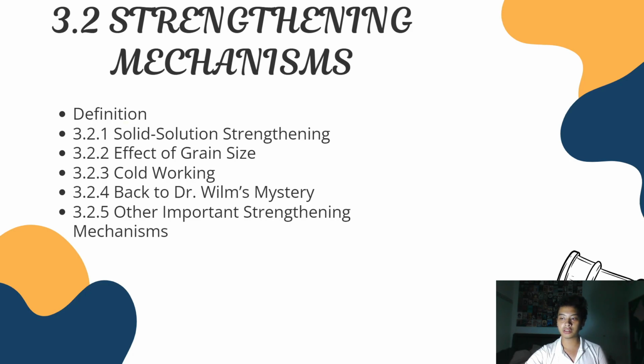Solid solution strengthening. Solid solution strengthening is a mechanism that increases the strength of a metal through the careful addition of specific alloying elements. The insertion of substitutional and/or interstitial alloying elements produces a strain in the crystalline lattice of the host solvent structure because the solute atoms typically have a different size than the host atoms.